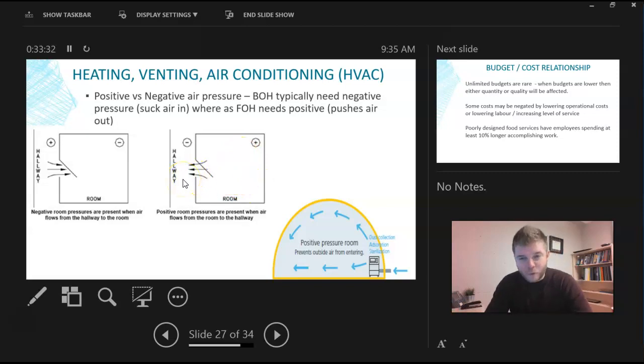Now, why this is important is because it comes down to two situations. One is contagious disease. So if you have a contagious disease, such as COVID, you would want the inside air staying inside the room, and you want positive air out into hallways. So this is used in a hospital environment quite often, where all of the outside air in the hallway can come into the room, but the COVID-infected air perhaps in this room will not go out. Okay.